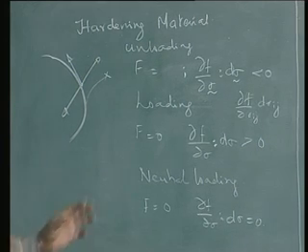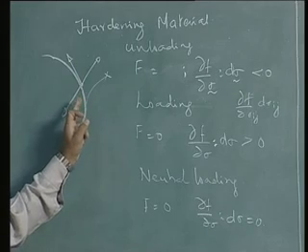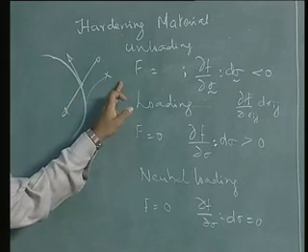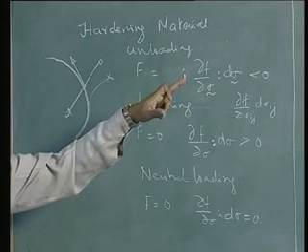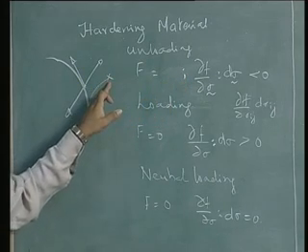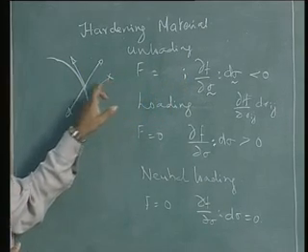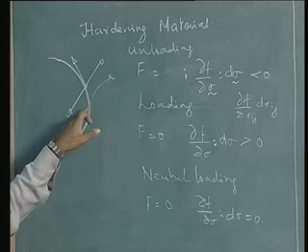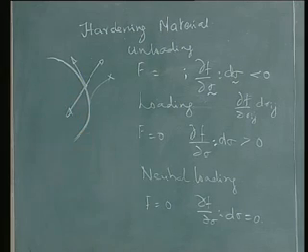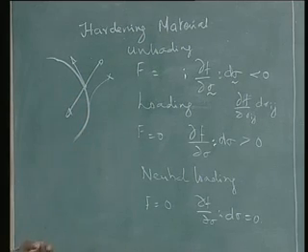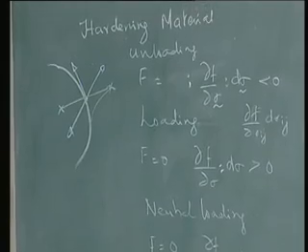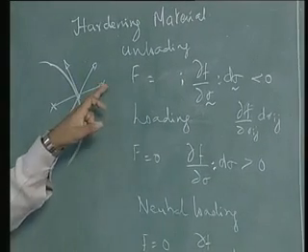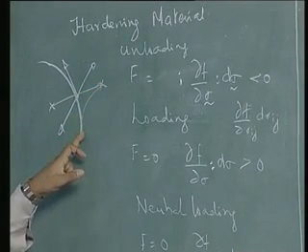So is that clear? That it is possible for a point to lie outside the yield surface for a viscoplastic case. In other words, the consistency condition is not satisfied, but with time this point would fall back into the yield surface. The behavior which takes the point from inside the yield surface to outside is an elastic behavior, and when it falls back, it would be a viscoplastic behavior.